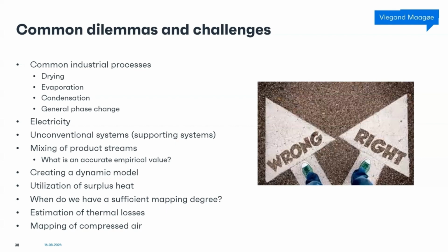We had an example of a textile factory where a sewing machine was operated on compressed air. There could be a number of good arguments why it should be operated on compressed air due to some process technologies. But if it's just a matter of operating it, having some energy converted, then it's very inefficient. You should definitely look at what the total cost of ownership of this sewing machine would be using compressed air. And I think you will discover relatively fast that by converting this into direct-driven electricity, the payback is relatively low.